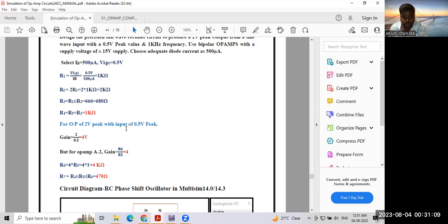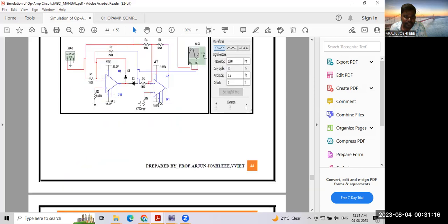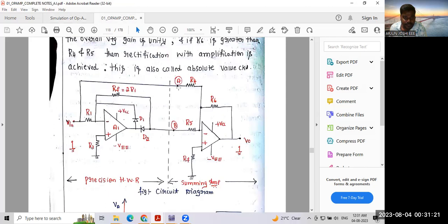Okay, what are we expecting in this? If we give 0.5 as input, observe here, VA in this condition, where will VA be? If I give 0.5 as input, then VB should be 1 volt, that is 0.5 into 2, because VB is equal to minus 2 into Vin. But the total output is VA plus VB, and VA plus VB is nothing but a total of 2 volts, according to our question.